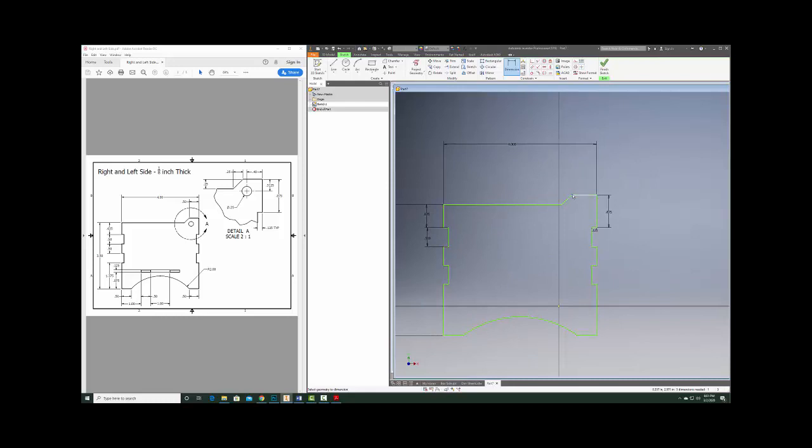Here I can click on corners too. This corner and this corner, and if I pull up 0.25, I can see that dimension I'm pulling from right there. If I dimension again, click on the same two corners, but this time go this way. Oh, it already knew that, so we're good. I can leave or delete it. We're good. But this should be a 45-degree angle, so that makes sense. Right here, 0.5. Okay. Actually, we're looking pretty good.